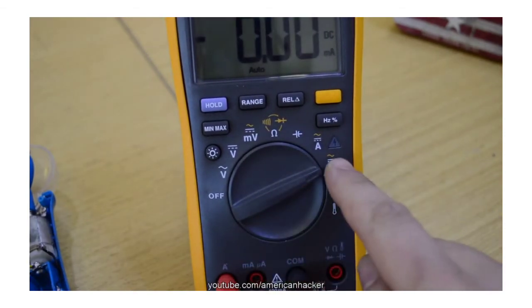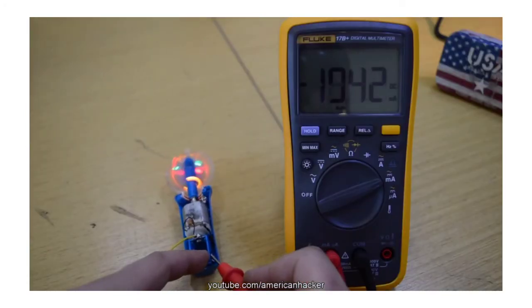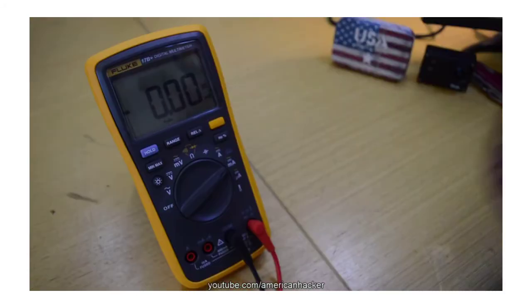In order to see how much current is flowing through some device, you have to cut the wire and set the multimeter in series with the flow and read how many amps the device is pulling.